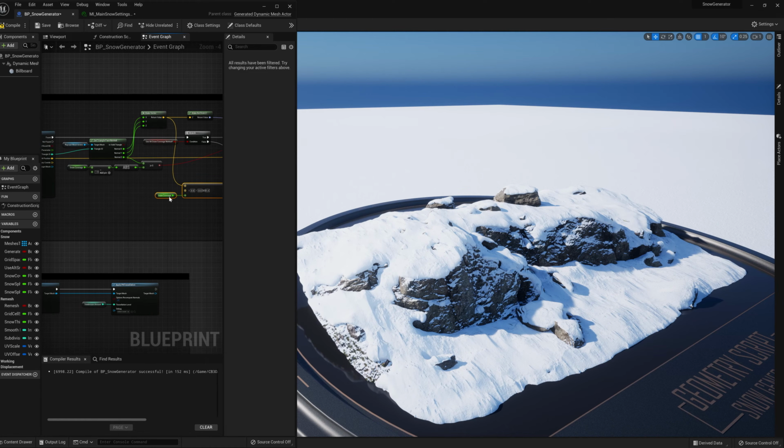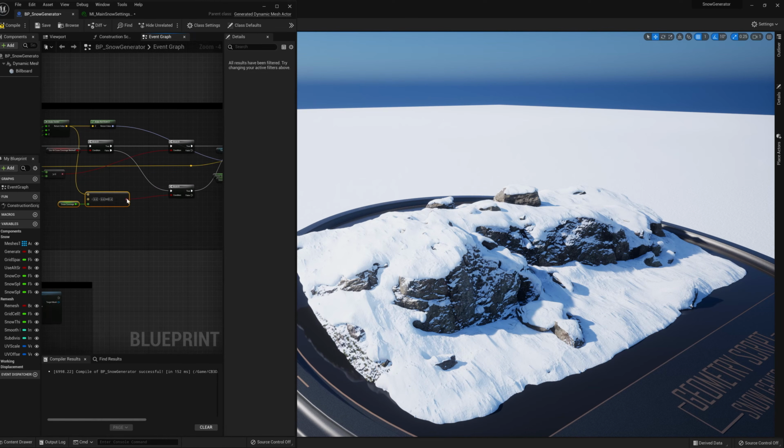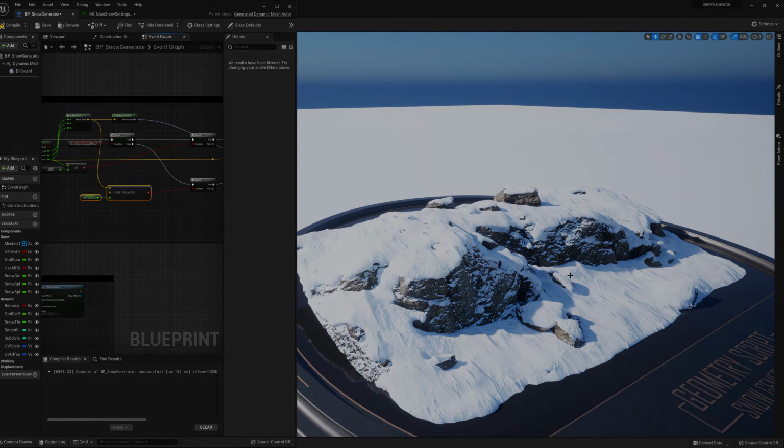One thing to bear in mind is that the coverage value used between these two different methods will provide completely different results because of the way it calculates the normals. When I showed the first method, the one before this one, I used 0.6 in coverage, but for this one, which is using this section, I used 0.2. I just wanted to show a different way, and how you can really easily add additional things into the node graph and make quite significant changes to the way things look.